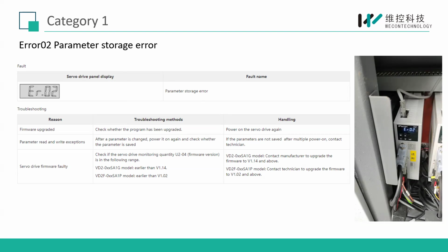And then the other situation: for the VD2 SA series, if the firmware is earlier than V1.14, and for VD2F, if the firmware is earlier than V1.02, for these two, please upgrade the servo firmware to solve it.